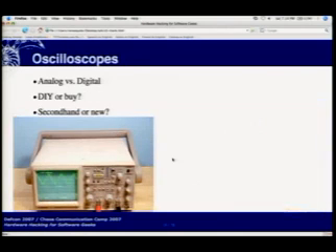Another useful use for an oscilloscope is when you're debugging your PCB layouts and you're looking for EMI, which might be affecting the operation. So you don't know why it doesn't work, and you've double-checked your logic 15 times. You might find that interference from, say, your power supply part of the board is coming in on your analog inputs, and it's not properly isolated with the grounding, and the components are too close, and you might get some signal leakage even though the traces are isolated, but they're just too close on the board. So that will show you exactly what is on that wire, and what is on all the other spots without having to guess.